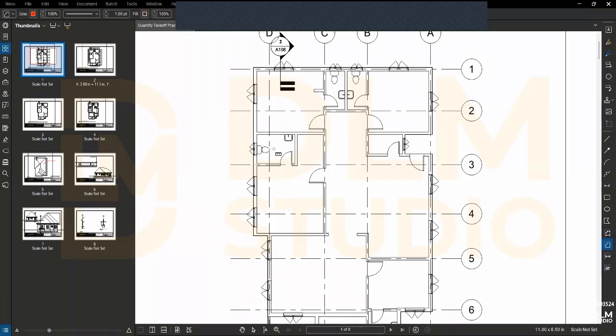Now, I want you to take note of this. There are some standard dimensions in building, such as the internal door to rooms, which is mostly 900 mm. So in a situation where you don't have the building dimensions, you can use the door width to dimension your building. That's one thing I prefer doing the most. Now you see this door here, it is 900. You see the internal door, which is a room, 900, and we have this at 750 for toilets and washroom and the likes. 750 for store, then 900 for second entrance, 900 for the rooms also, which is by default.